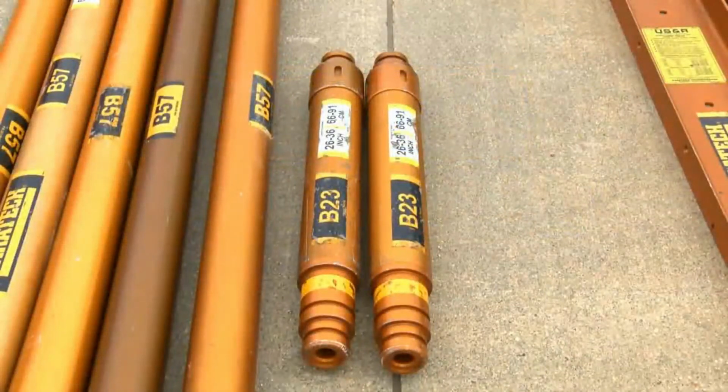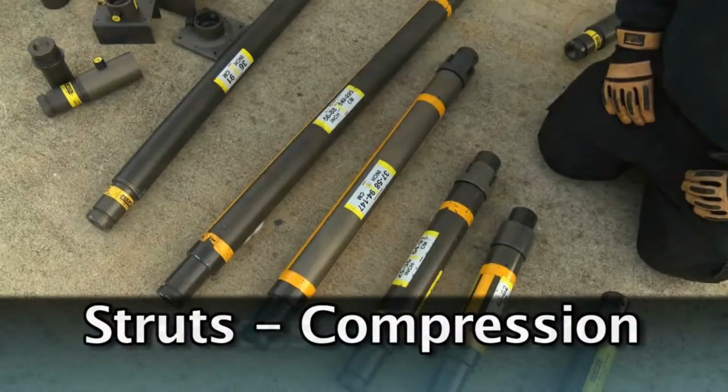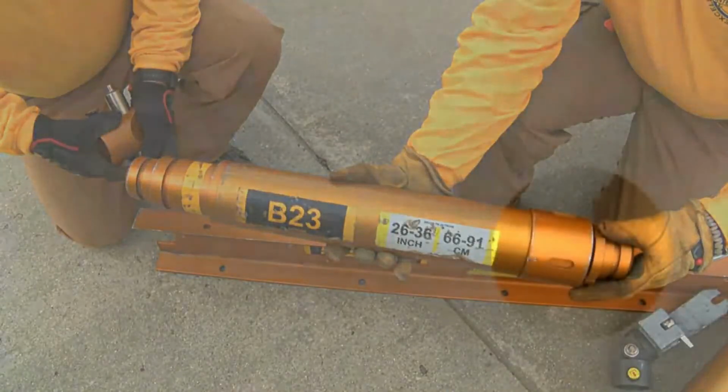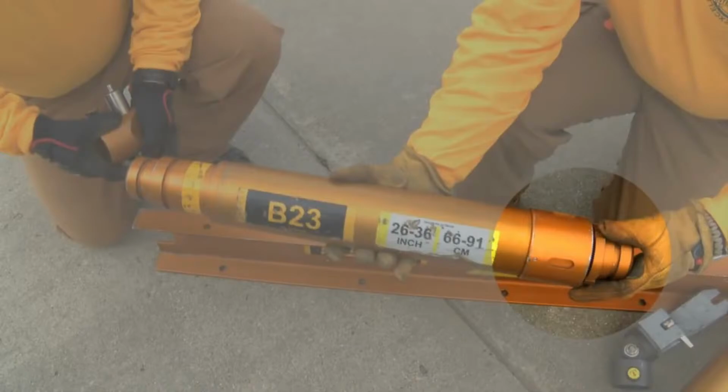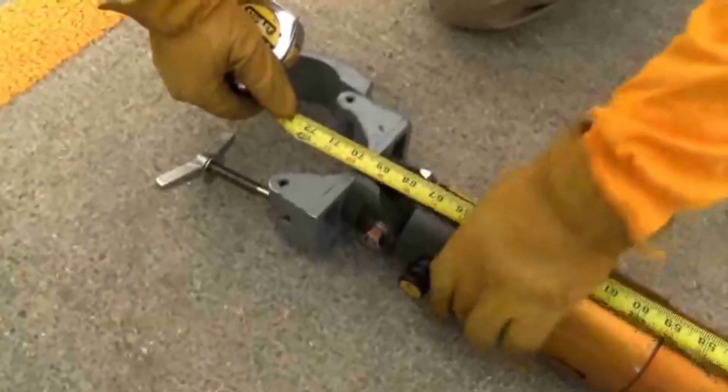A brace is indicated by the prefix B before the number. The difference between a Paratech strut and a brace is that struts are designed to be used in compression. Braces are designed to be used in tension. The collar of the brace is permanently attached to the tube. To adjust the brace, you spin out the piston. The collar does not move.